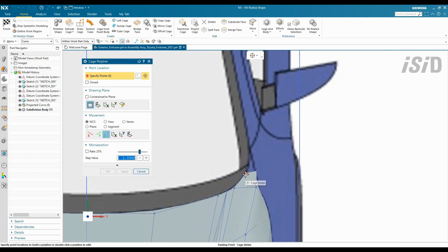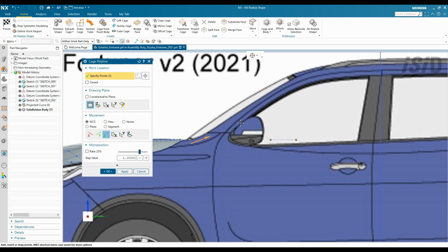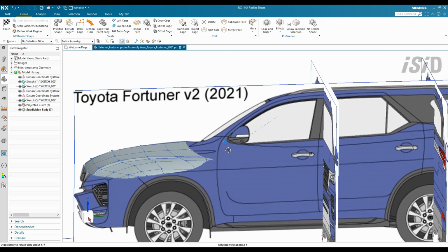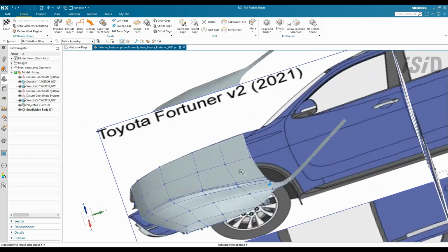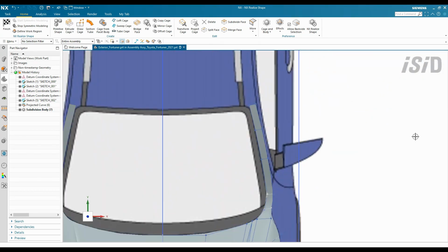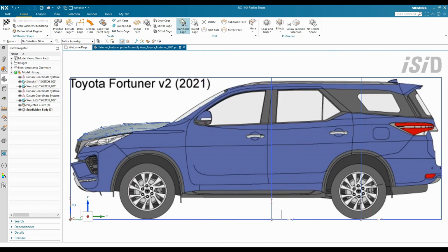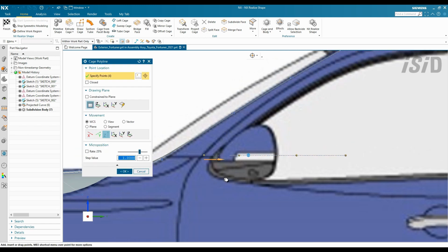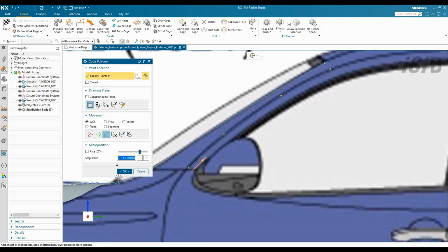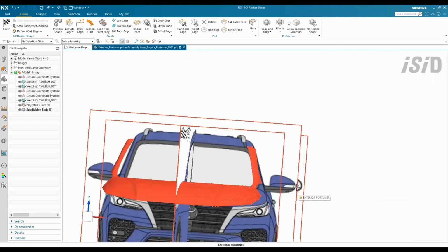And again, I continue to create these pillars using the same step, cage polyline, and then using sweep command, and again using cage polyline, repositioning the cage polyline using transform cage, and then connect it using loft cage.